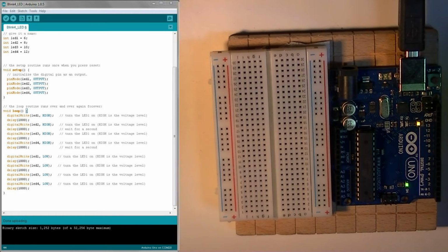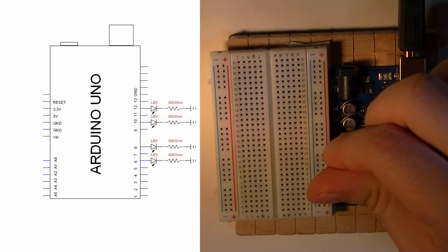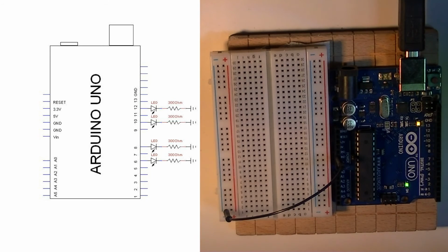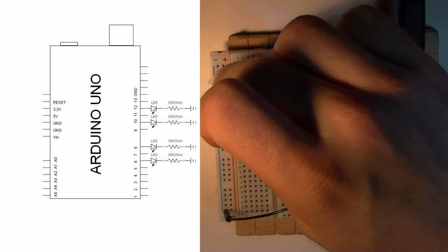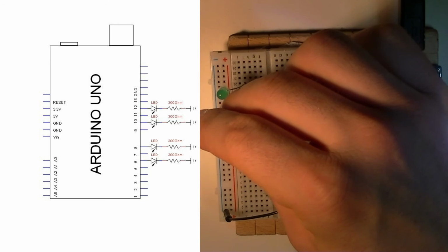Okay, so now we're going to upload the program on the right, which is essentially going to give us a panel of 4 LEDs that we can program to do what we like. At present, if you look at it, it essentially turns on 4 LEDs one by one and then turns them off one by one, which creates a bit of a pattern. So to get started, as usual, we connect the blue rail on the breadboard to the ground. Now we're just going to plonk 4 LEDs in with their short legs in the ground and the long legs into the breadboard. We're just going to spread them out nicely so that they create a reasonable pattern.